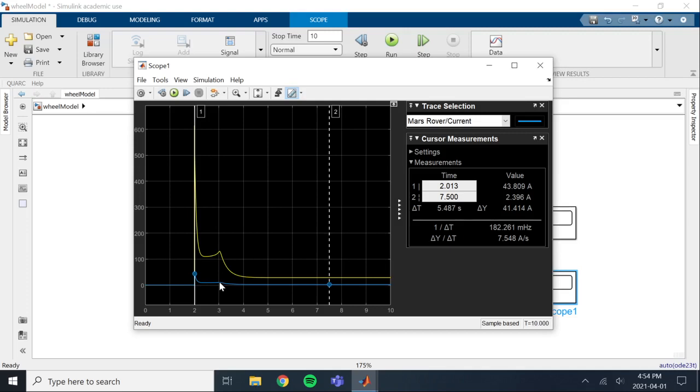So eventually when we have 6 motors working at the same time, taking the same duty cycle, because we are going in the same direction, same speed, that is going to be 43 times 6 amps, which is pretty close to 300 amps, which is ridiculous and way over what we can provide on our rover. So now that we know this, we know that we can't actually operate going from 0% duty cycle to 100%, but that's fine.